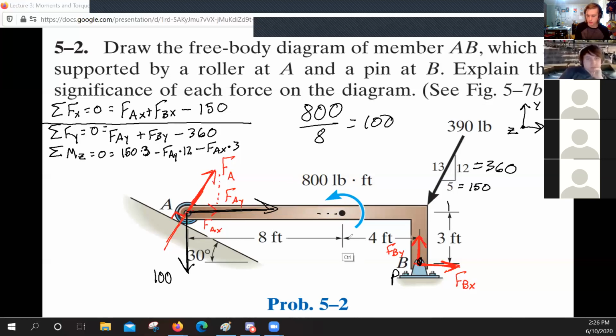that's what's perpendicular. Okay. So basically, I'm just taking this moment and splitting it into its distance and force, and then now that I have a force over here, I can reapply it to our pivot point, which is P. And the way I'm going to do that is I'm going to say the distance here is 12, and we have a 100-pound force that is 12 feet away.